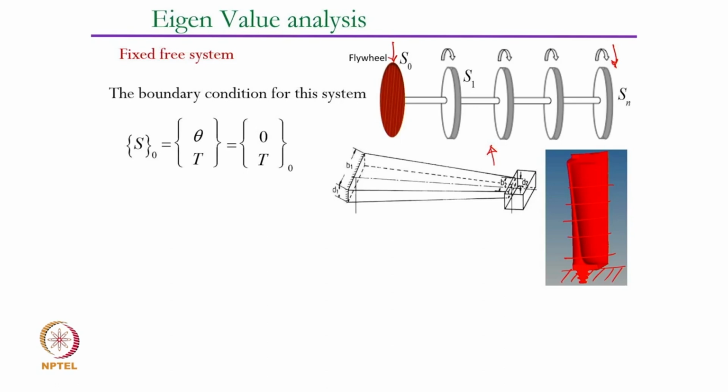Can we say that the flywheel being so heavy, we can treat that end condition to be a fixed end condition? We have seen that in vibratory system modeling, a simplifying assumption could be that if the inertia of the flywheel is large enough, we can treat it to be almost rigid. If that is the case, the twist there will be 0,